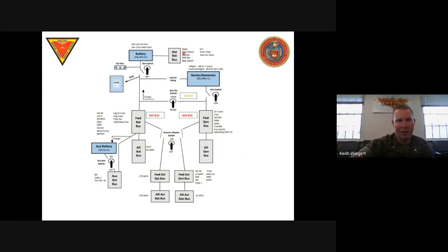Your OBOGS itself doesn't stay on, but it is controlled via a different switch. You get your actual OBOGS switch, which means that the engine doesn't have to be on to turn your OBOGS on, right? Which is like, if we have an engine out at a high altitude, cool, we can use battery power to power the OBOGS to continue breathing if we're up there until we get down below 10,000 feet. Your FDR, that's your flight data recorder.